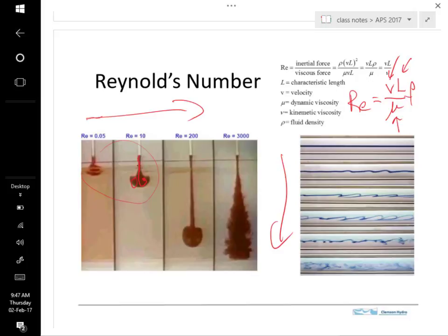So laminar condition doesn't necessarily mean that the flow is all just straight. You can have vortices forming, but there are these kind of stable vortices that are formed from the geometry of the flow. But what's not happening in this case, that is happening here, is that you have a whole array, or a whole range of sizes of vortices. This kind of cascade of vortices from large to small that'll characterize the turbulent flow.